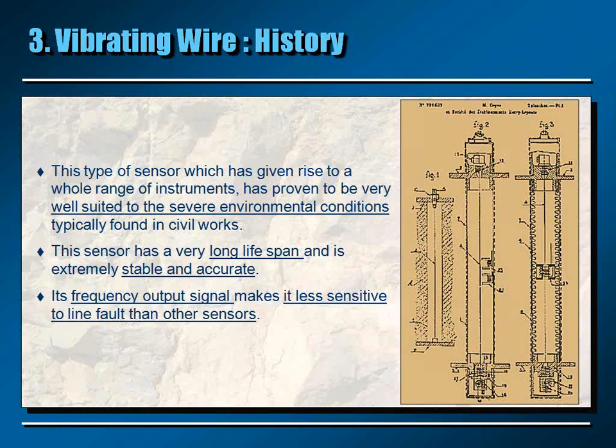So it shows that that's an interesting feature, because as you know, when you embed or install a sensor in concrete or inside of a dam, you wish the sensor to work for a long time. You don't want to be forced to replace it every 5 years or 10 years. So ideally, you will wish that the sensor will last as long as the structure itself. So the vibrating wire technology is appreciated for that.